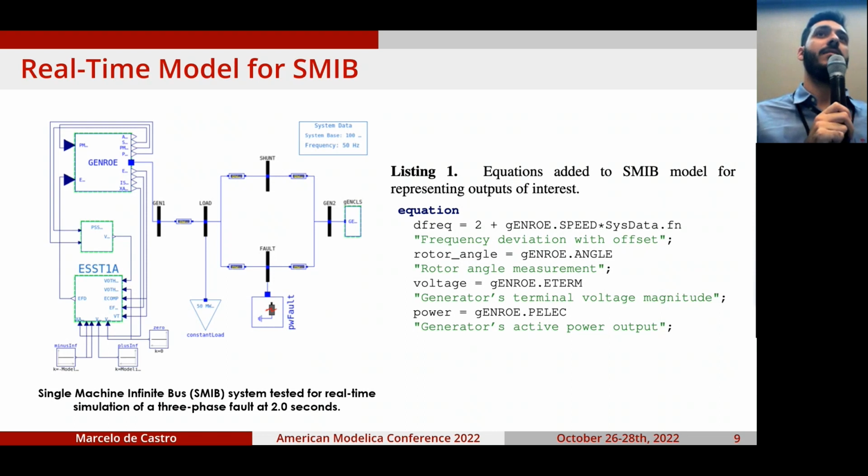And this is basically because we are measuring it using the output I/O board from the real-time simulation, so we are actually using the oscilloscope, and we actually need displacement because the I/O board doesn't comply with negative voltages. So we just shift them up just so we can measure everything without any distortion.